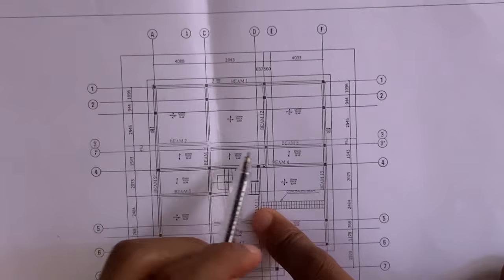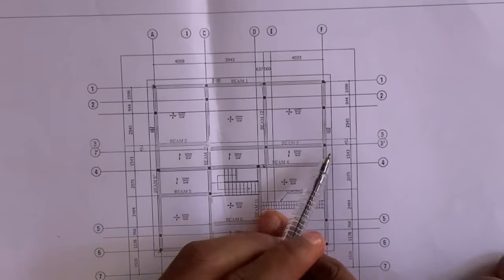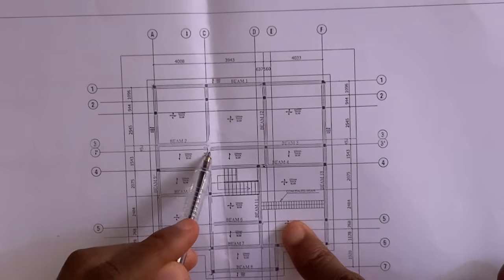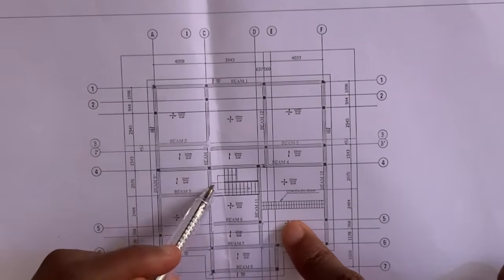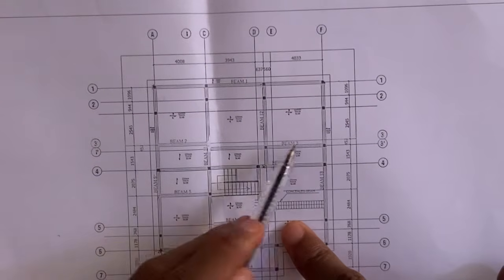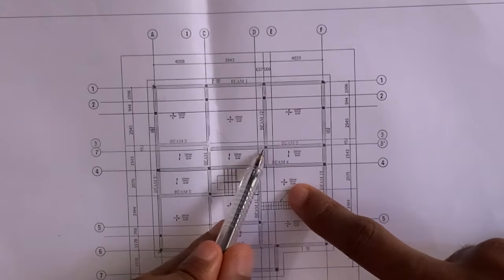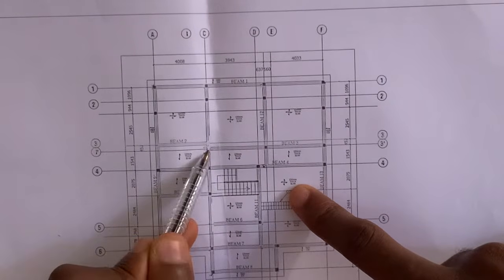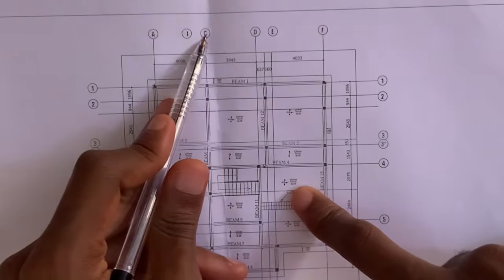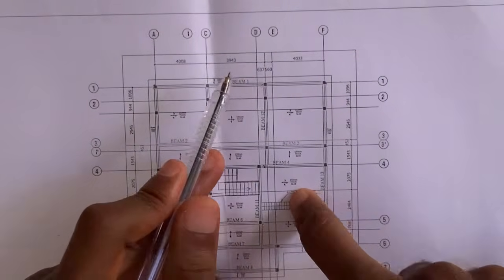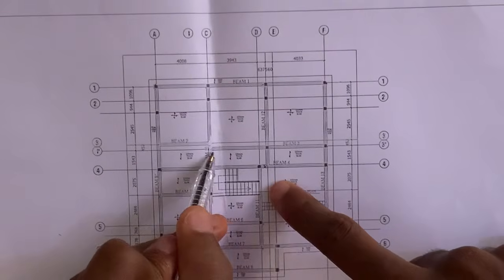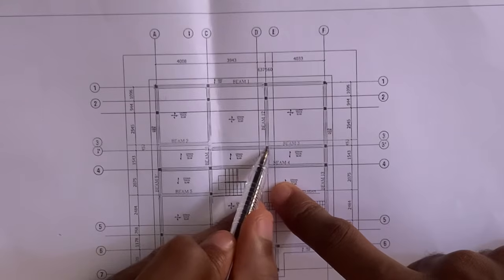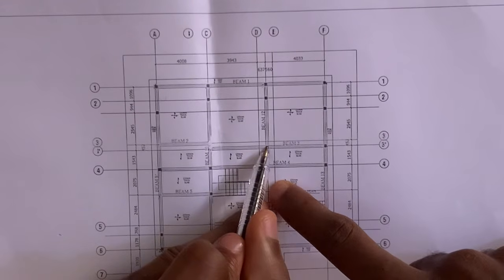And you can see that Beam 3 is intersecting what? Two columns, this column and this column. However, at this other end, it is intersecting this vertical beam here, which is Beam 10. So now, we already calculated that the dimension from this point to this point, which is from callout C down to this point, is 4,580, right? So it means that the dimension from the center point of this beam here down to the center point of this column is 4,580.